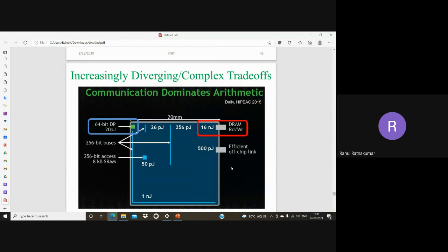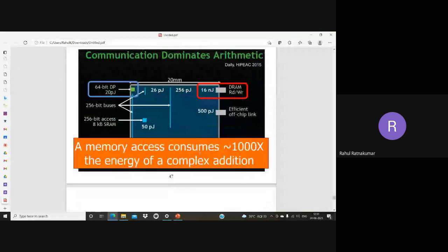So a lot of power consumption is delays causing problems. One solution is we can reduce our voltage VDD or VCC. But then we don't have much swing. What is swing? Our VDD is 0.9 volt to 0.7 volt, which is actually very difficult to work with because we don't have much noise margin. Because when noise comes, our one becomes zero, zero becomes one, and there are a lot of challenges. So this is the main catch.